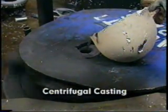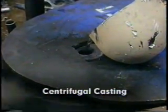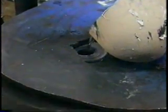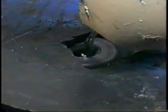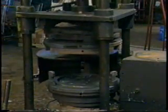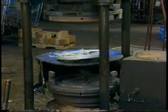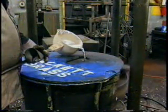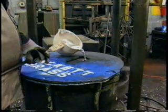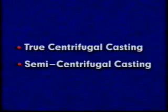Centrifugal casting is the solidification of molten metal under the centrifugal force generated by a rapidly rotating permanent or expendable mold. The high force typically results in denser castings than are produced in static molds. Virtually all metals can be centrifugally cast. There are several types of centrifugal casting methods, including true centrifugal casting and semi-centrifugal casting.